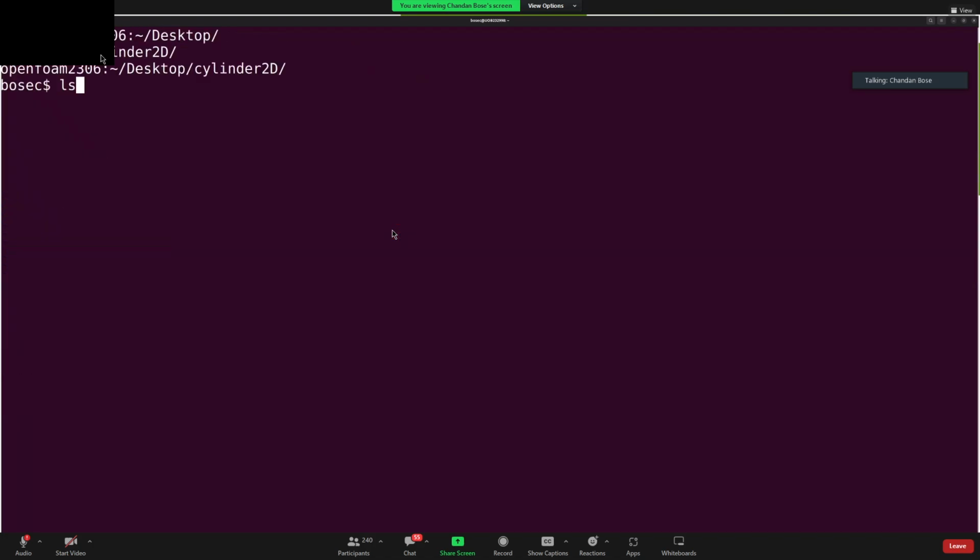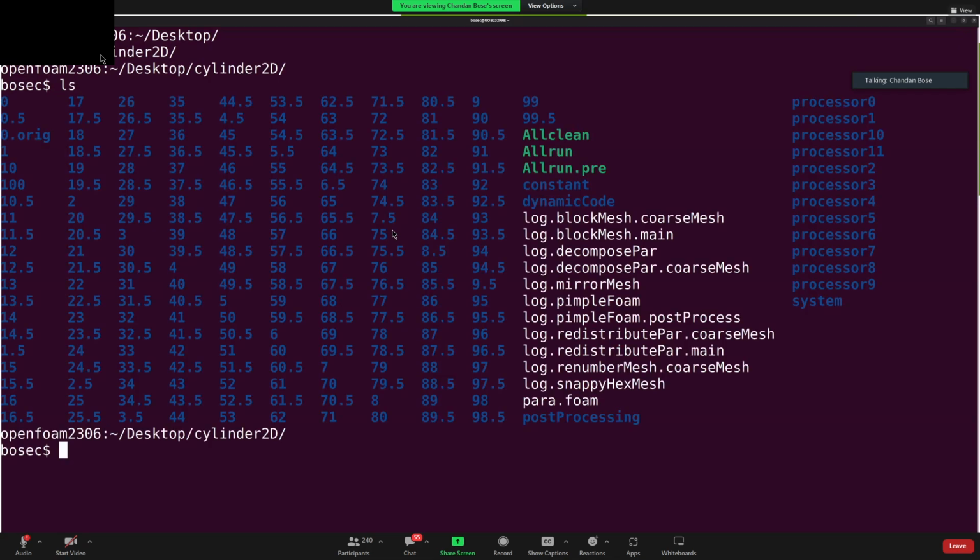All right. So this is a simulation of flow past a cylinder, and the meshing has been done using snappyHexMesh. However, in the interest of time, I don't have time to show you how to mesh it using snappyHexMesh, which also falls into intermediate learning and is a bit involved. So once you know how to do it properly with blockMesh, then you move to snappyHexMesh. But I want to end this session with a visualization showing you the mesh created by snappyHexMesh and what we can observe physically as vortex shedding.